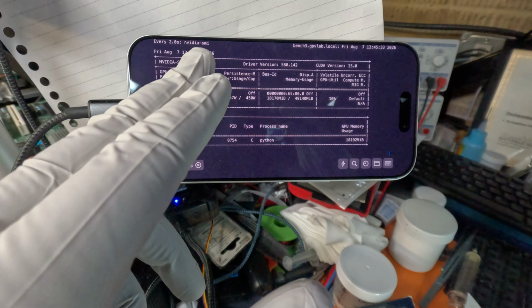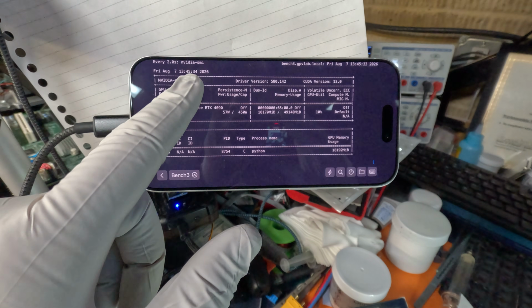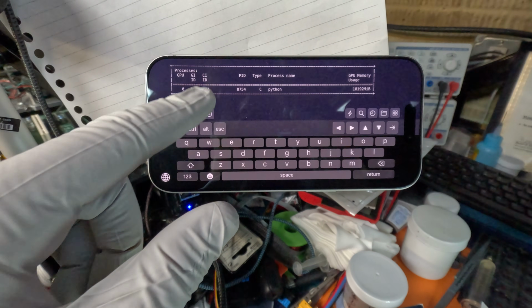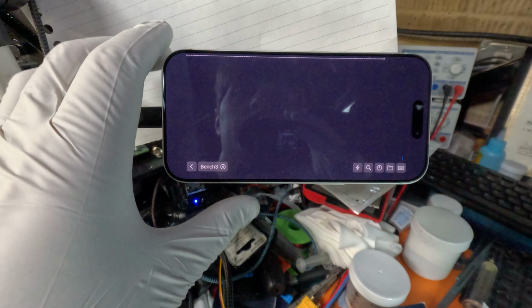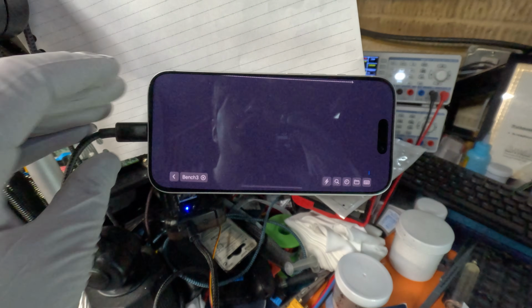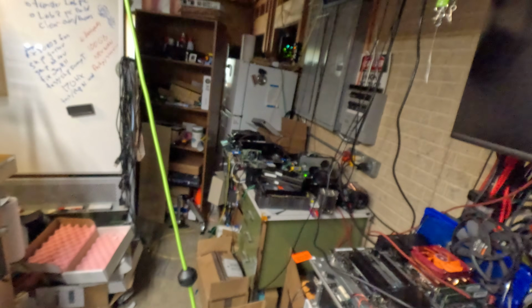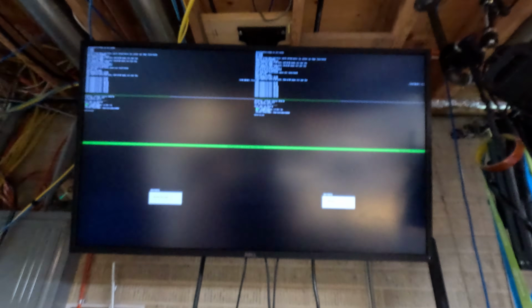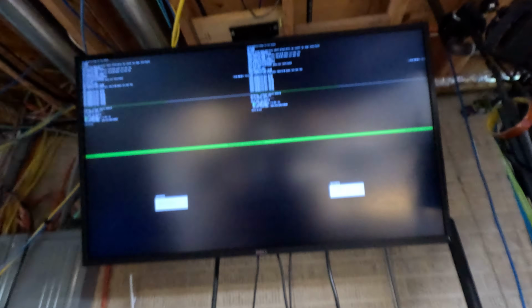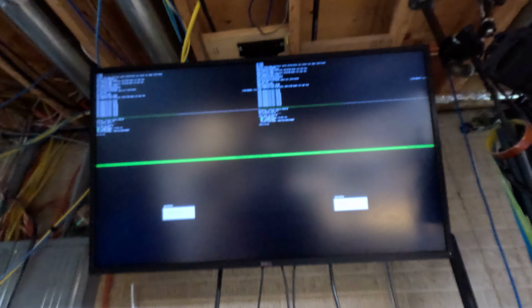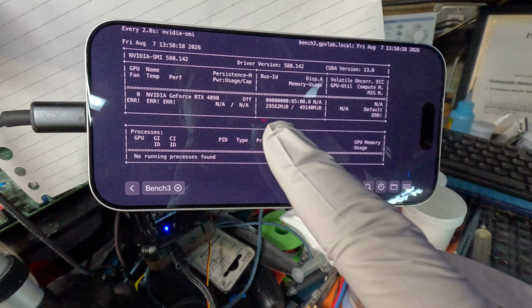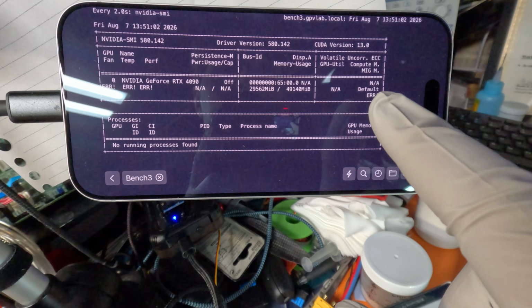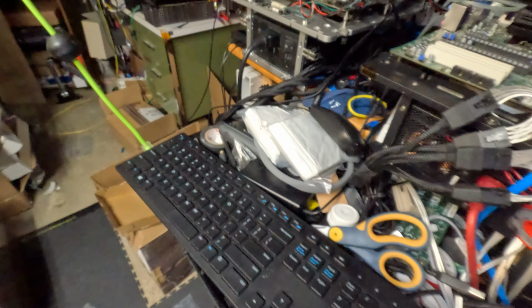And now, is it even updating? So it looks like we can't even call NVIDIA SMI because we have the timestamp. It's stalled. Oh, and now my session's frozen. We can see that the program that I have monitoring NVIDIA SMI has also stalled out. So what happens typically after this point is that it comes back after a few minutes, and then it shows that the GPU has fallen off the bus with some kind of memory issues. Here we see after a few minutes the card comes back with the error symbols, and typically it's going to ask for it to be reset.